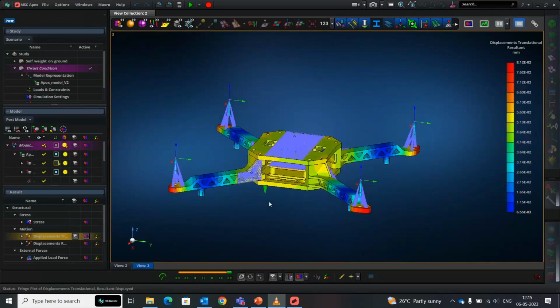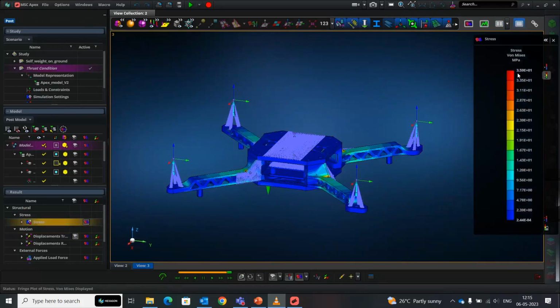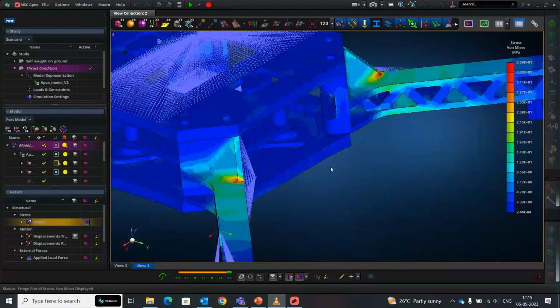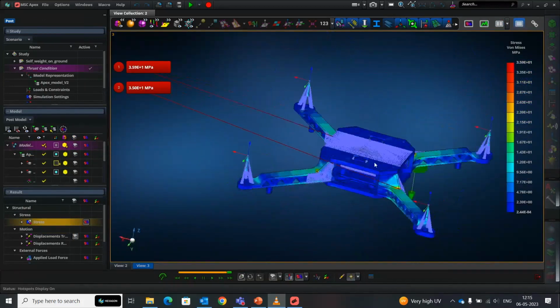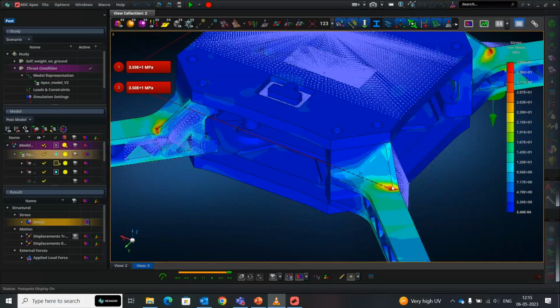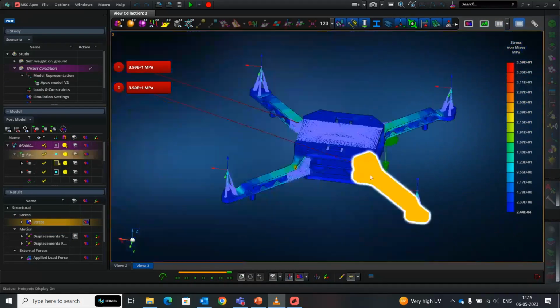And you'll be able to see the value of your translation deformation and also the stresses incurred. The stress is not too much. You're getting about like 35.9 MPa in a von Mises stress. So this is okay. So your loading condition is absolutely okay for your application need.